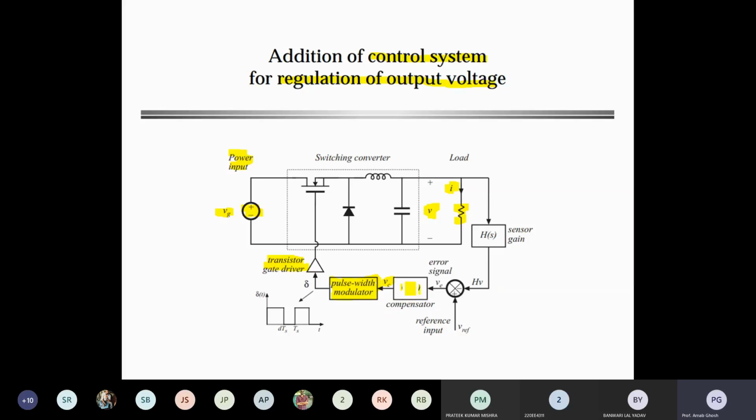So what is your load regulation expression? Load regulation equals VNL minus VFL, whole divided by V nominal, into 100%. What is VNL? It is the output voltage at no load. VFL means output voltage at full load, and V nominal means nominal output voltage. So no load voltage minus full load voltage, whole divided by the nominal output voltage, which is your reference output voltage, Vref.